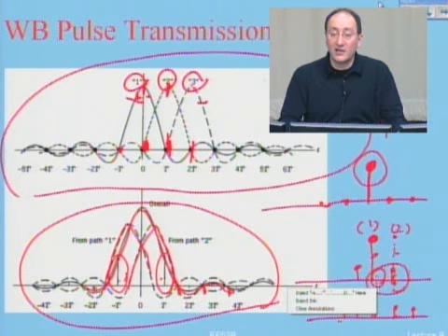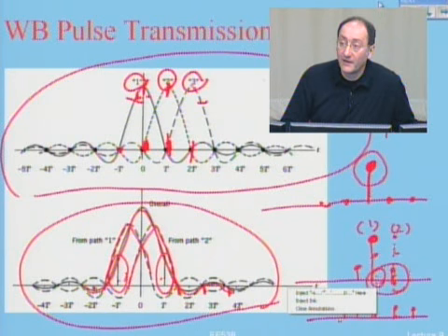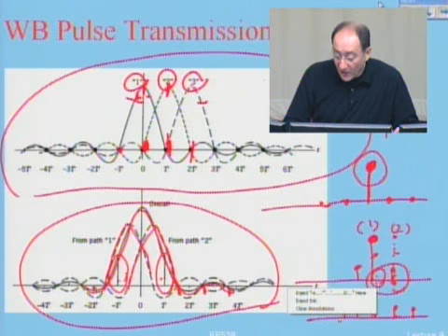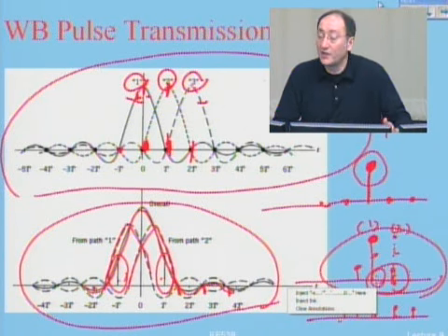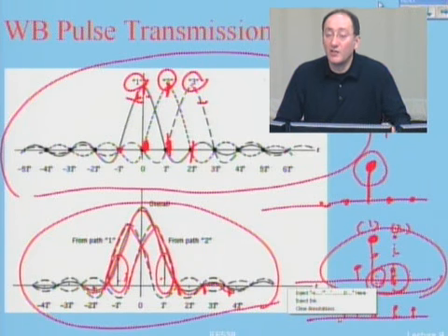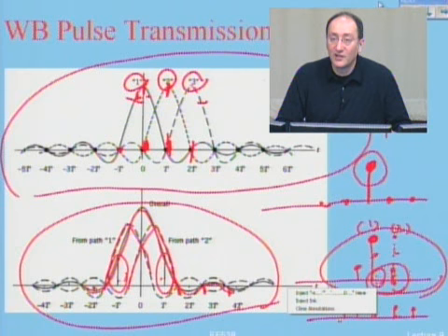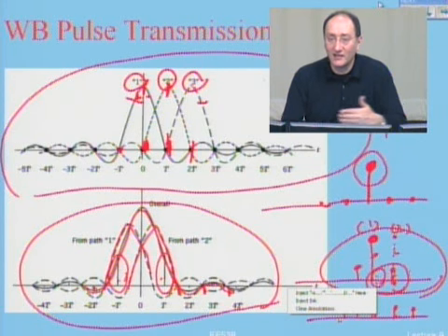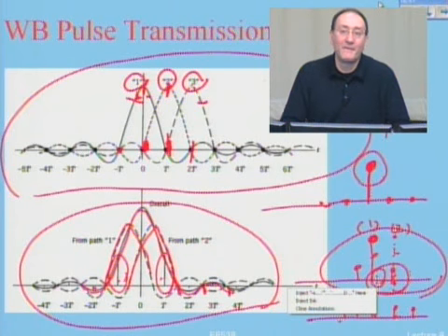Well, not necessarily, they could be correlated, but could even be independent. So if I'm smart in wideband communication, I can take advantage of diversity of the signal. Because in wideband communication, my discrete impulse response has more than what? More than one tap. So each of these taps looks like an antenna. They fade differently from one another. So I have a source of diversity.